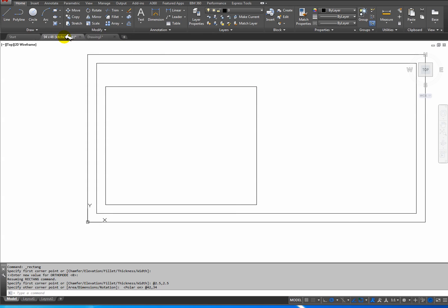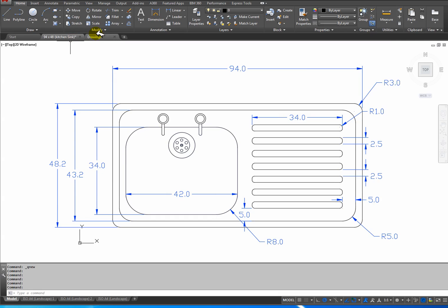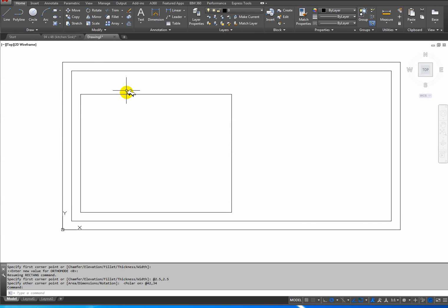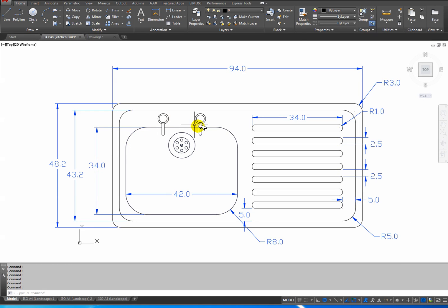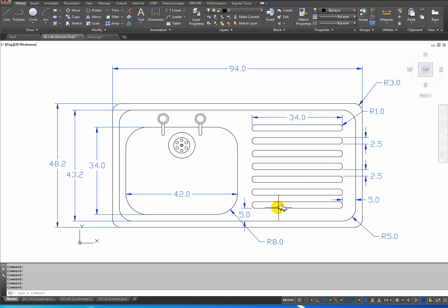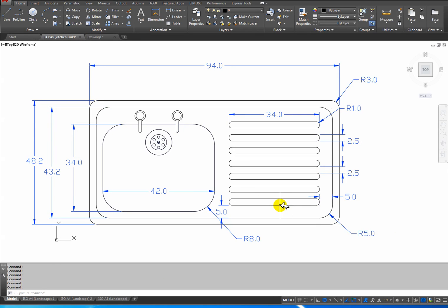So we managed to create this rectangle using something called the relative and absolute coordinate system. I'll explain that later on before I finish this tutorial. So I've done this, I created that, and the next part is I'm going to create these rails. I'll only start with one, and then I'll create the rest of them using a tool called array.